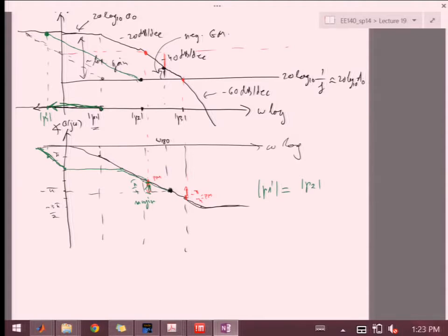So remember what we talked about when we talked about the unity gain bandwidth, right? For a single pole amplifier, we had this curve that was 20 dB per decade. And however much you move from the unity gain, that's how much in frequency back, that's how much your gain increases, right? So here, we want to move so much back that our gain increases by how much? From 1 over f to A0. So by how much is that? What is this difference here?